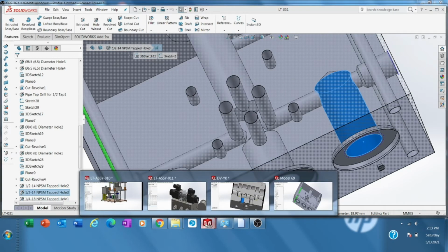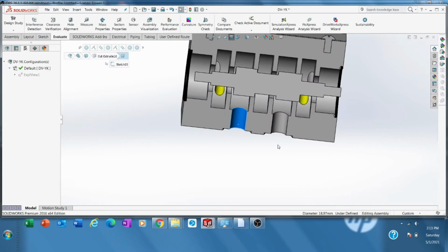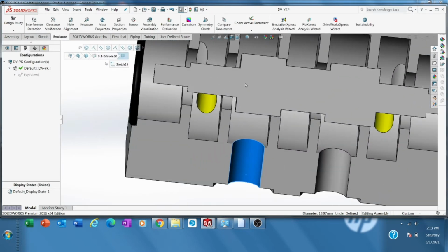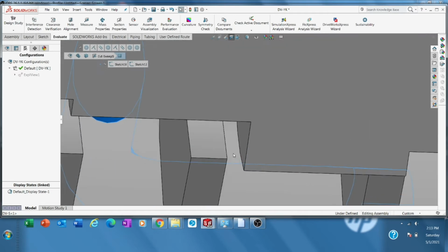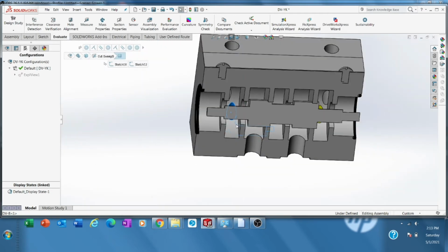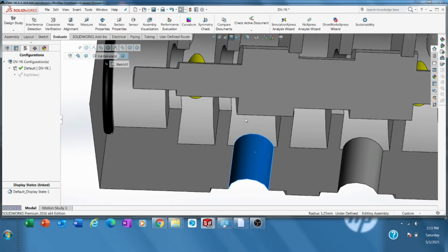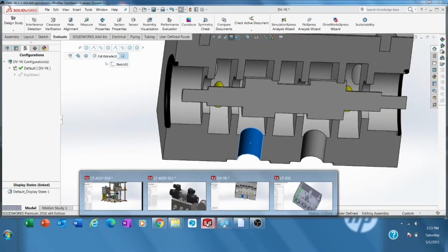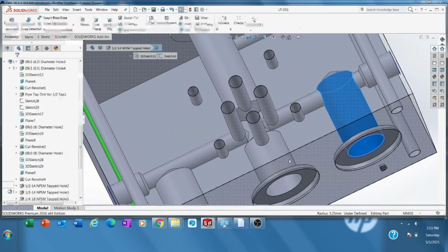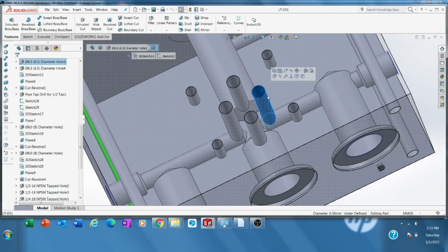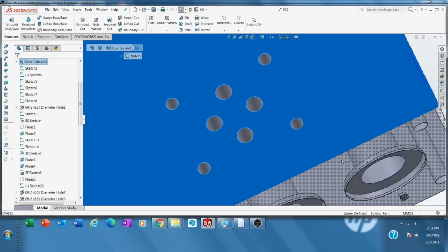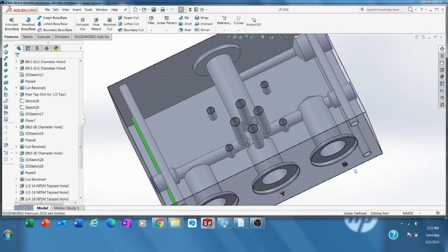So we can check again from this directional valve. When the spool moves here, the fluid from the pump moves to here because there is already an opening here, and flows to here, and then from that hole in the manifold, moves to here, here, here, out here.